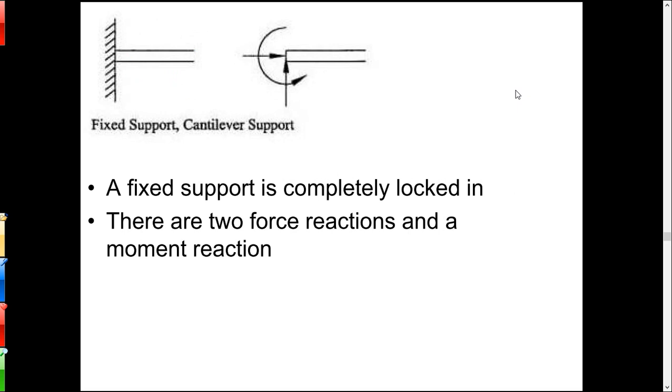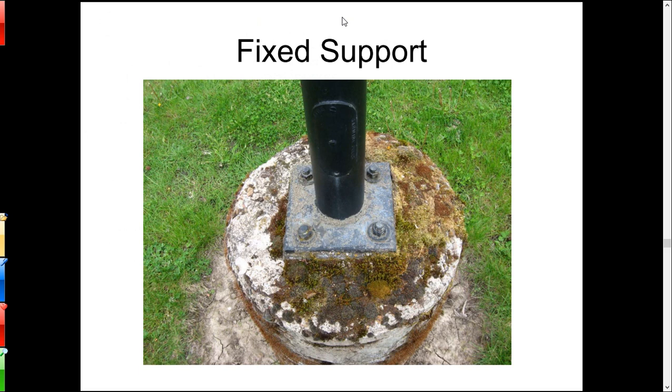Okay, a fixed support is called a cantilever support sometimes too, completely locked in. So in 2 dimensions, there are 2 force reactions and a moment reaction is shown there. Okay, so that's a fixed or cantilever support. So there's a fixed support. It's bolted down into that concrete pillar. This light pole here is not going anywhere. It's not going to move left, right. It's not going to move into the page and out of the page, nor will it rotate. It can't do anything. It's all locked in.